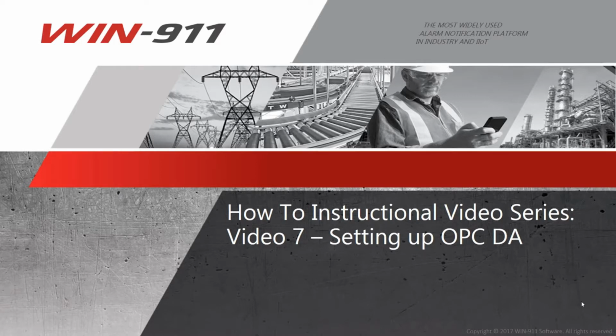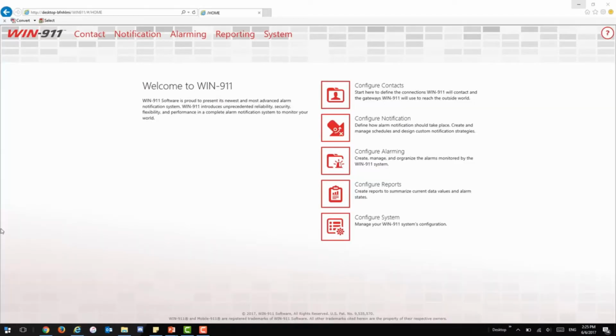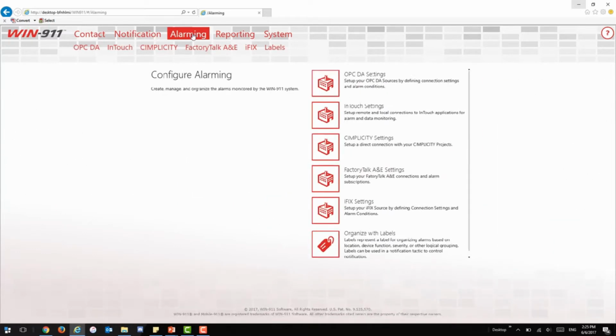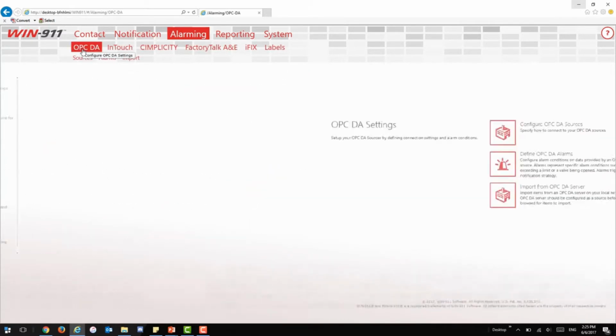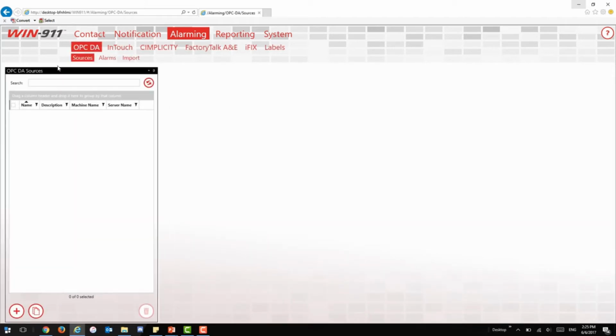This is video number 7, and in this video, we're going to be covering setting up an OPC DA connection. All right, so if you'll open up your configurator, we'll walk through this. You can get there either by going to Configure Alarming here, or Alarming at the top, and we're going to select OPC DA. And we're going to start with sources so it knows where the information is located.